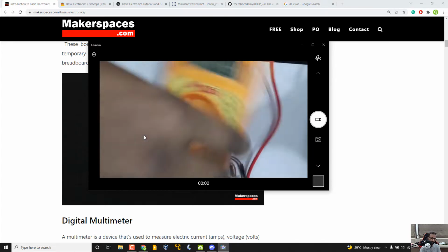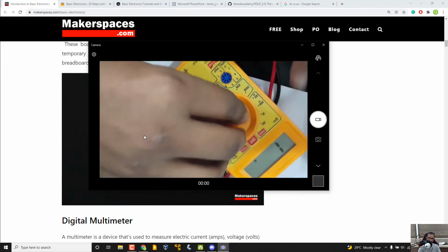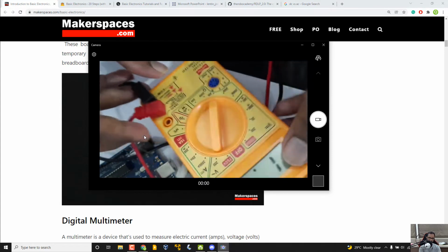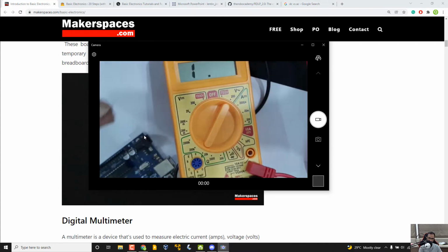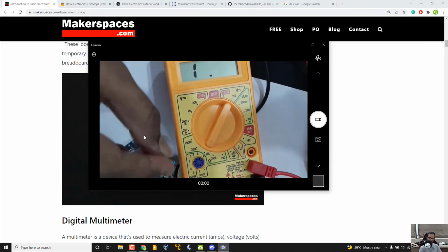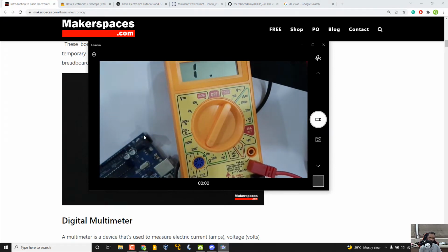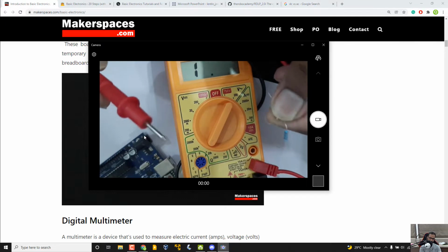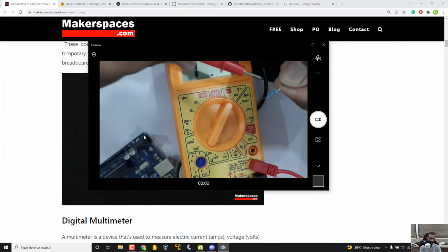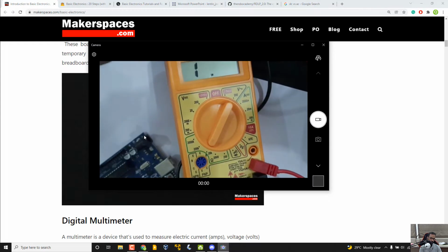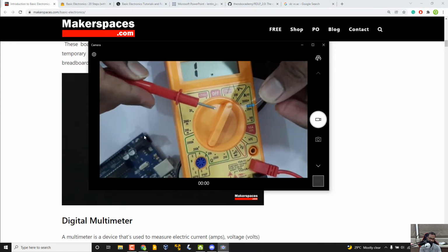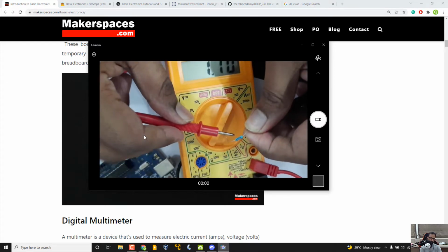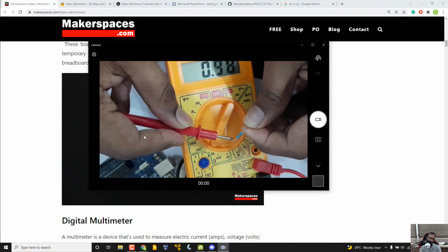is I can just switch on the multimeter, then set the range to 20K. Okay, 20K is the range that I put. That means the multimeter can detect up to a 20K resistor. So I can just use these two terminals, positive and negative, placing the resistor in between, like this. So you can see a resistance value there.